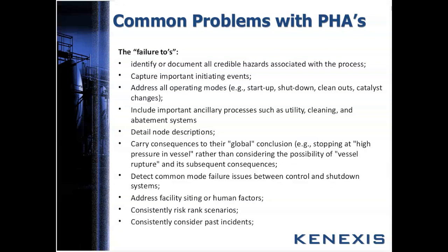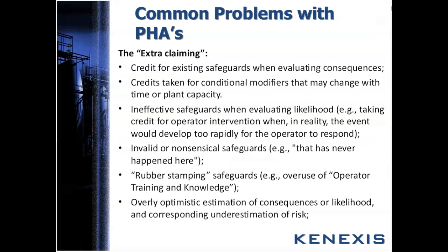They don't consistently rank the scenarios. They don't cover past incidents. Okay? And then this is where you really give too much credit where it's not deserved. Over-claiming. Claim extra safeguards or conditional modifiers. In other words, people are really around all the time, and you may say, well, they're not around very much, so you may add a factor of 10 in there to compensate.